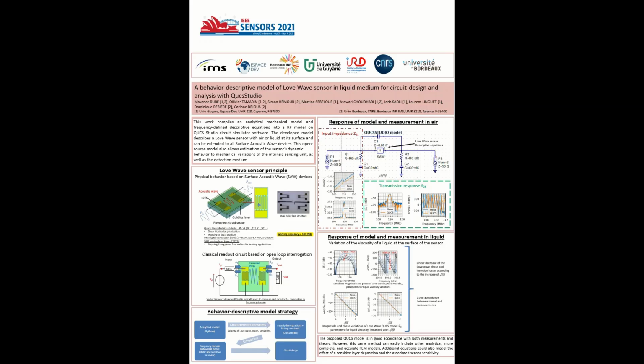In this work, we try to use different equations to obtain a descriptive model for Love wave sensor for QUCS Studio. This simulator can be used for basic RF and circuit design and is really similar to the ADS software. However, QUCS Studio and this model are completely open source and free to use. We integrated both the response of the sensor in the air and the response of the sensor in liquid medium, and the model can be used to simulate both mechanical and electrical behavior of the Love wave sensor.